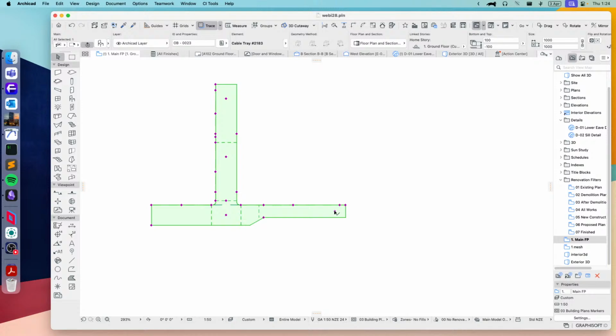This one here, which is sitting in the middle, you can see similar ones here, here, and here, will allow us to add new branches. So you can see at the moment we have a single branch, which is creating this T shape. If I move this up or down, it's going to create an upward pointing or downward pointing branch. So it will break this edge here, or rather, sorry, it'll stop this edge here. It'll put a branch going up and then a new branch heading off in the direction that we're already heading. So I click there and it will give us that new piece.